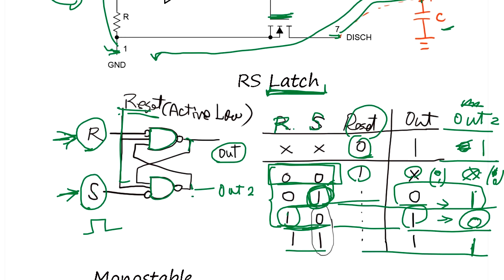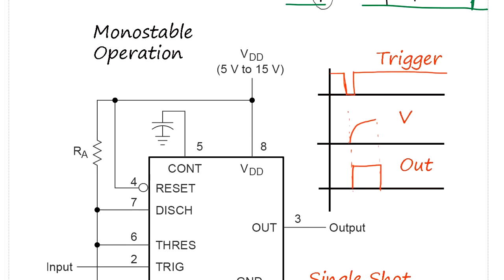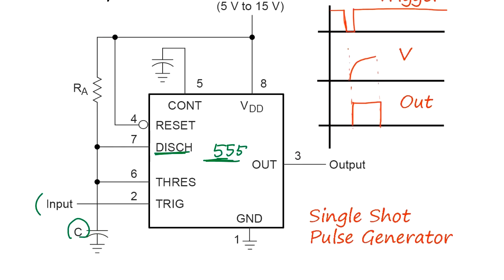Okay, so this is 1 bit of memory chip, actually. This is the 555 IC chip. This is the discharge point, which means it starts discharging. It short circuits to the ground. This is a C. Input is a trigger. And this is active low, which means when this goes low, the trigger is on and comes back. So this is connected to the set of the latch.